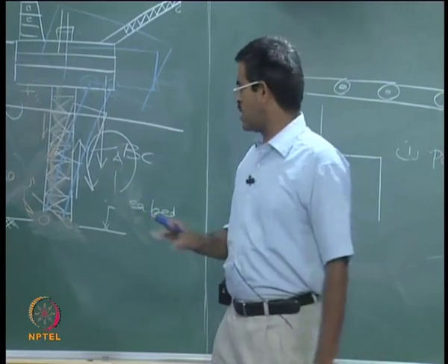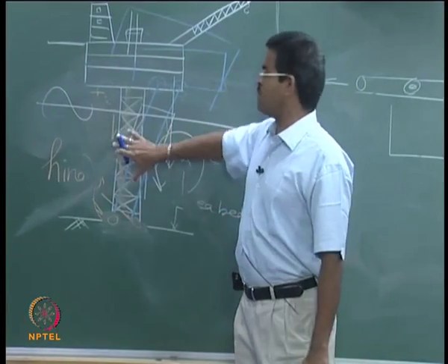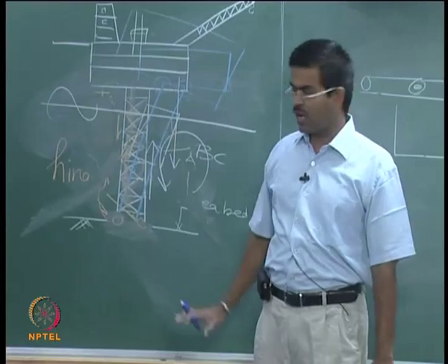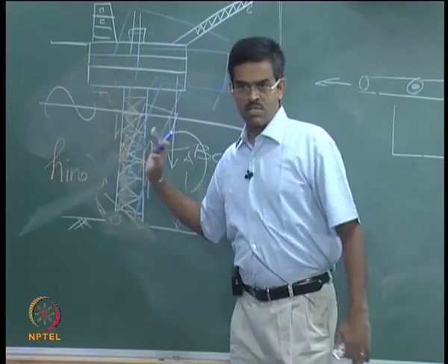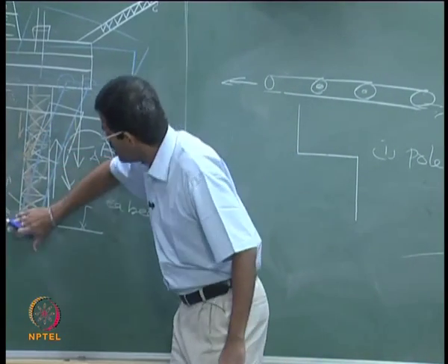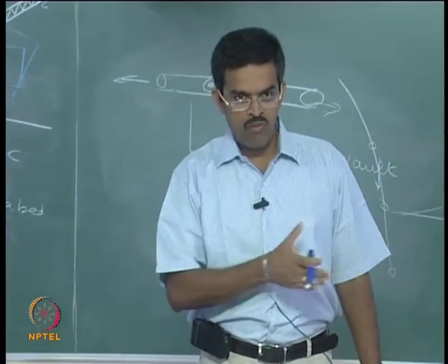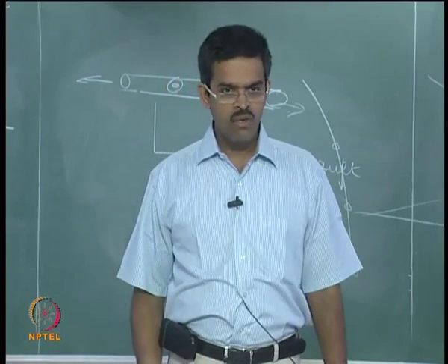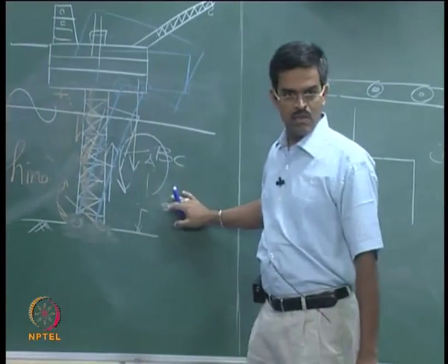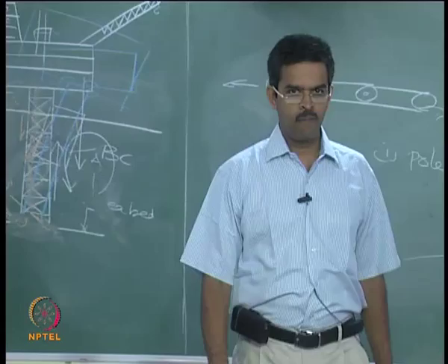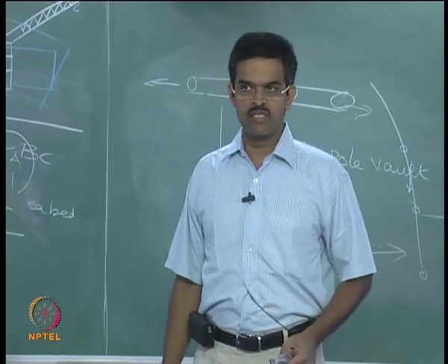If your focus is only to make it flexible, introduce the joints. If your focus is to make it restrained for loads, do not make it flexible by putting a hinge in between. So, there are multi hinge towers also available, multi leg towers available, and hinges only here available, hinges here and here available. So, structural form was evolved in such a way that people thought of introducing multiple joints and chambers and members to make it compliant. That was the whole idea, but this system has a demerit. I will come to that once we see some more slides here.